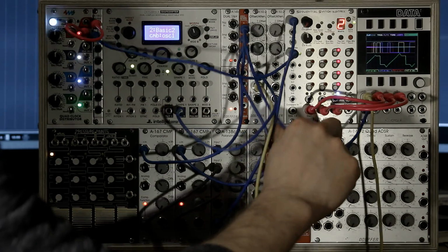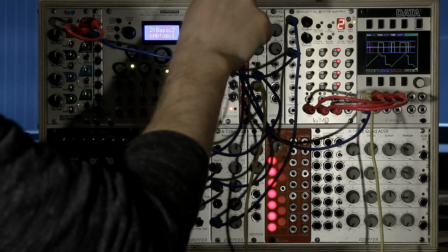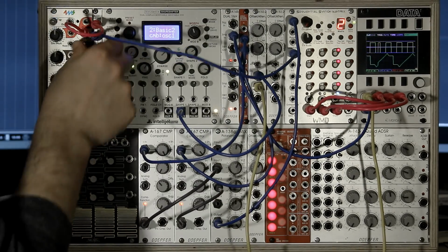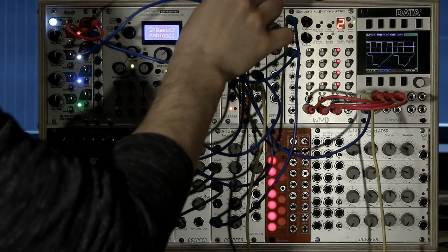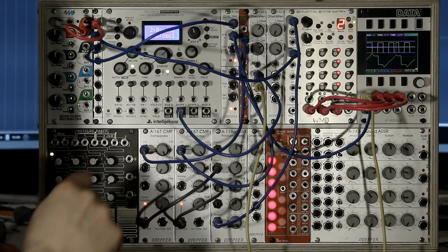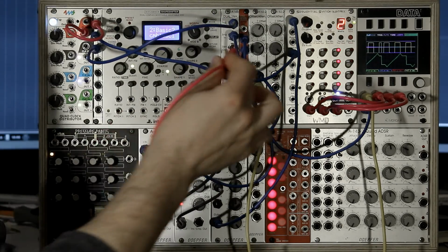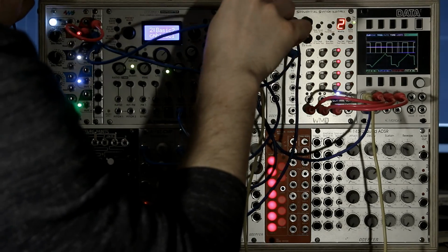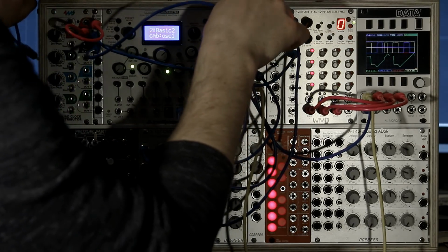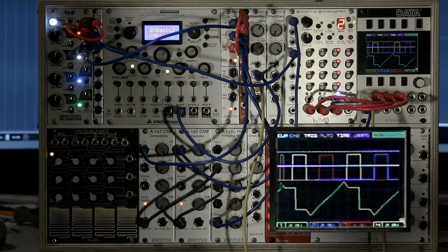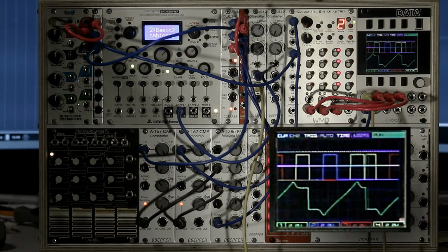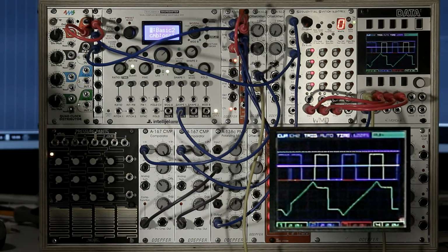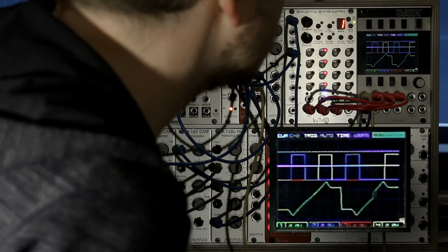I also want to keep the continuous signal on the display. I'll just insert sample and hold after the data display. And the trigger will be our main clock. And as seen on data, we now have a much cleaner result.